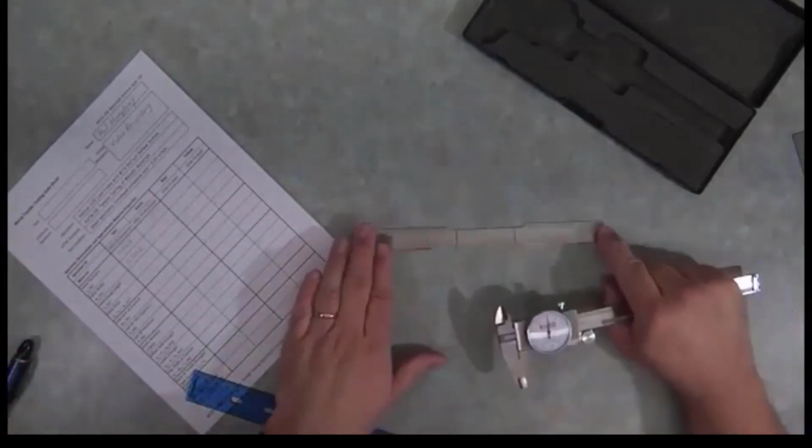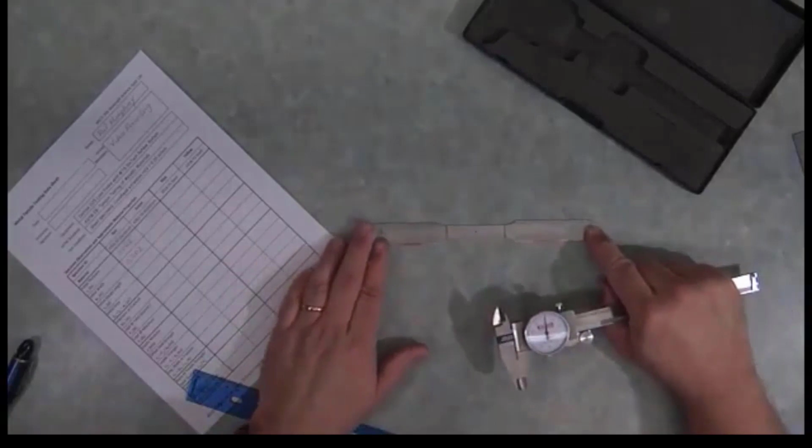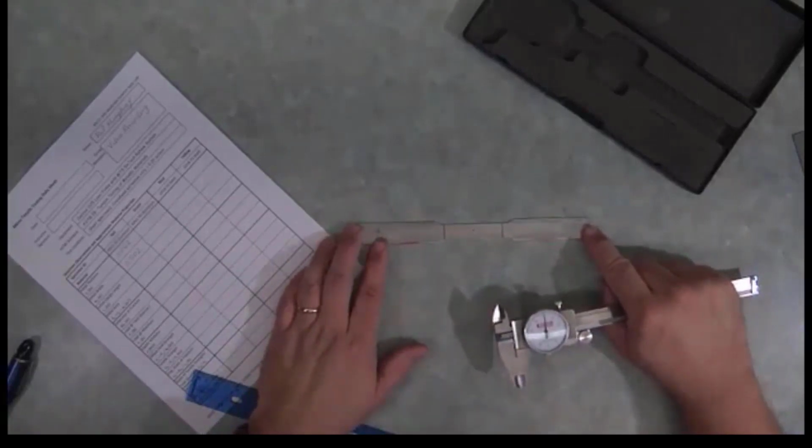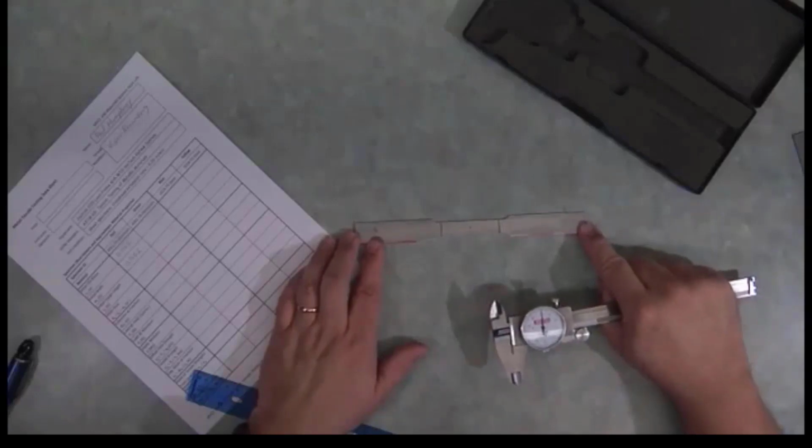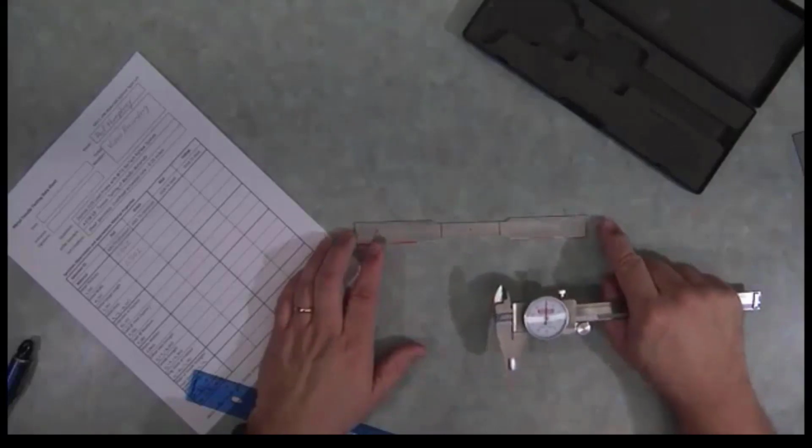And then we need the gauge length. Now, this is one of those small areas where we're deviating from the letter of the law in the ASTM standard that I mentioned. It requires that these gauge marks be 2 inches plus or minus 5 1/1000ths of an inch apart. I measured and drew them with a ruler, so clearly I'm not going to get 5 1/1000ths of an inch. We're not really worried about that for our purposes, but I do need to be careful that the line does have some thickness.